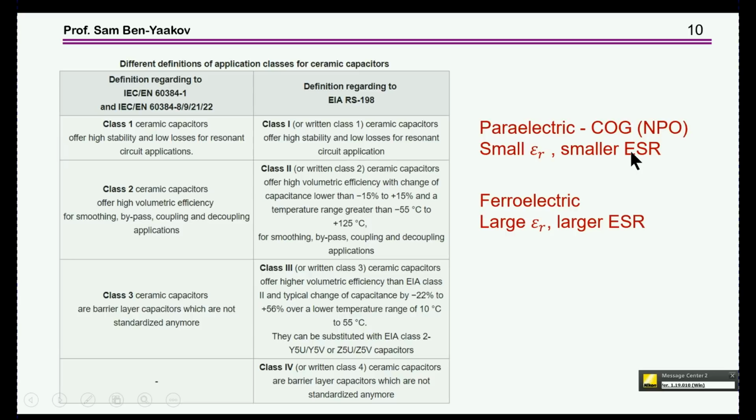In fact, today, the largest capacitor you can buy in the NPO family is something like 0.1 microfarad. Now, we want 10 microfarad, 100 microfarad, very large capacitances, and you cannot get them in a reasonable size with this capacitor. So whenever you can use it, that's fine. But unfortunately, in most of the applications, I should say, you just can't use it.